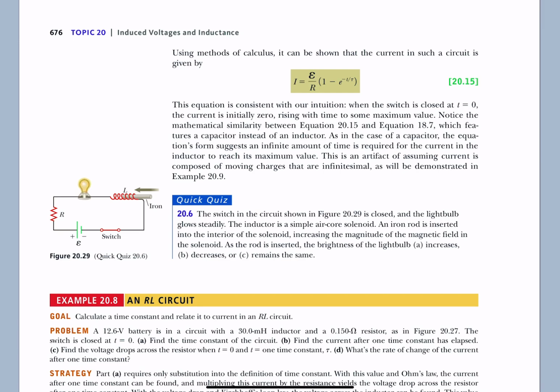Remember, in capacitors, we talk about voltages because it takes more and more oomph or push from the power supply, from the battery, to push the charge onto a metal plate that already has some charge on it. In inductors, we talk about current because it's the fluctuating current that causes the pushback from the inductor as the magnetic flux lines expand and contract.